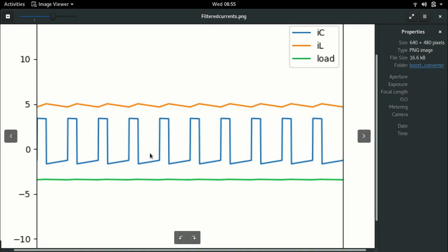So this is when the current reverses through the capacitor. And you will see that the current in the inductor will be the same as the current through the capacitor. Alright, almost the same, because now you see the capacitor is, even during this period of time, also discharging through the load, because the inductor current flows partly through the capacitor and partly through the load. This is the reason why you will see that there is a difference in magnitude between the inductor current and the capacitor current, because the remaining part is flowing through the load.